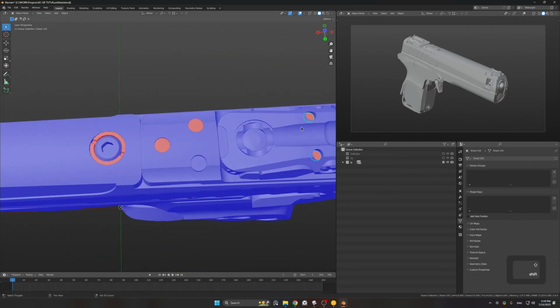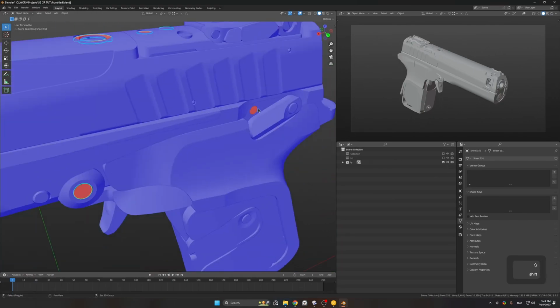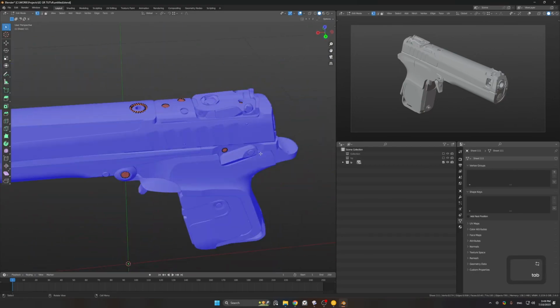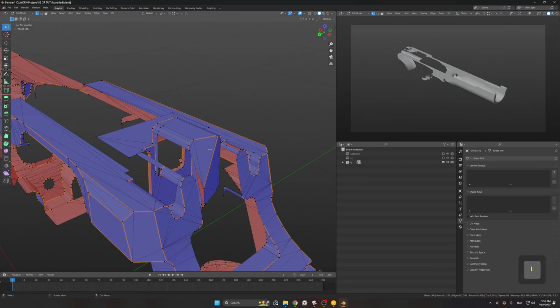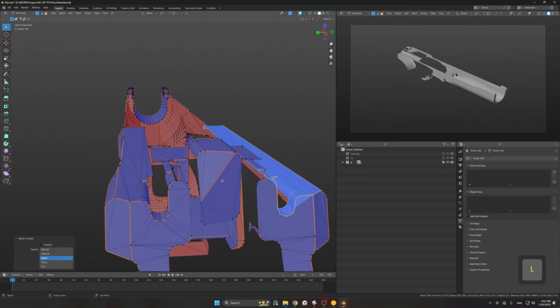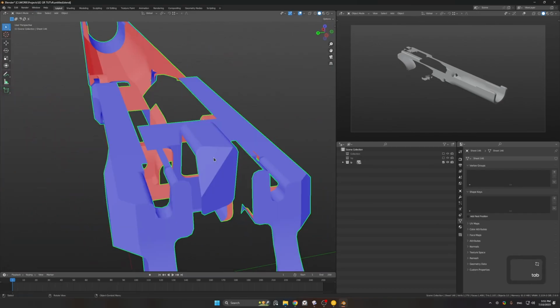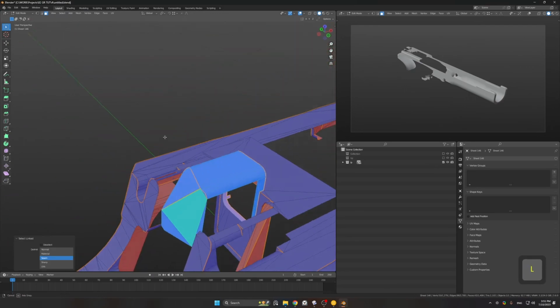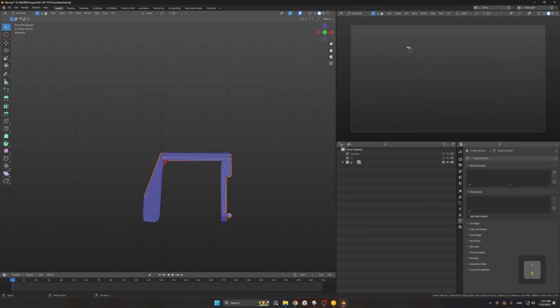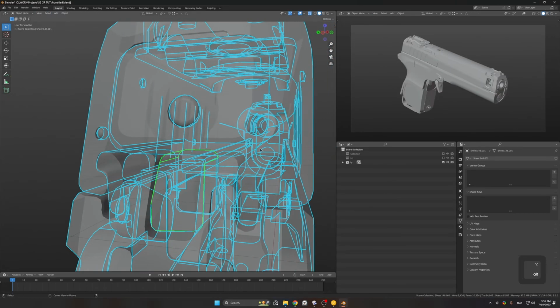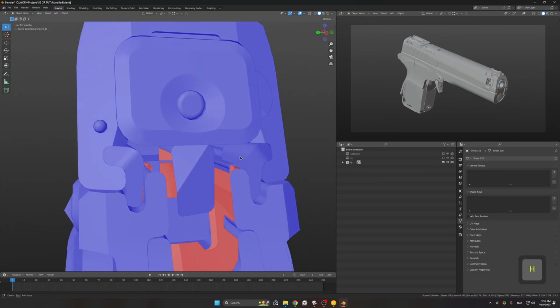Here we can see that some of the meshes have imported with inverted normals. We're just going to quickly fix that. Here we can see we made a little mistake where two of the separate objects are one mesh right now, and it's very easy to fix in polygonal software. So let's just separate it by selection and delete the rest that we don't need.